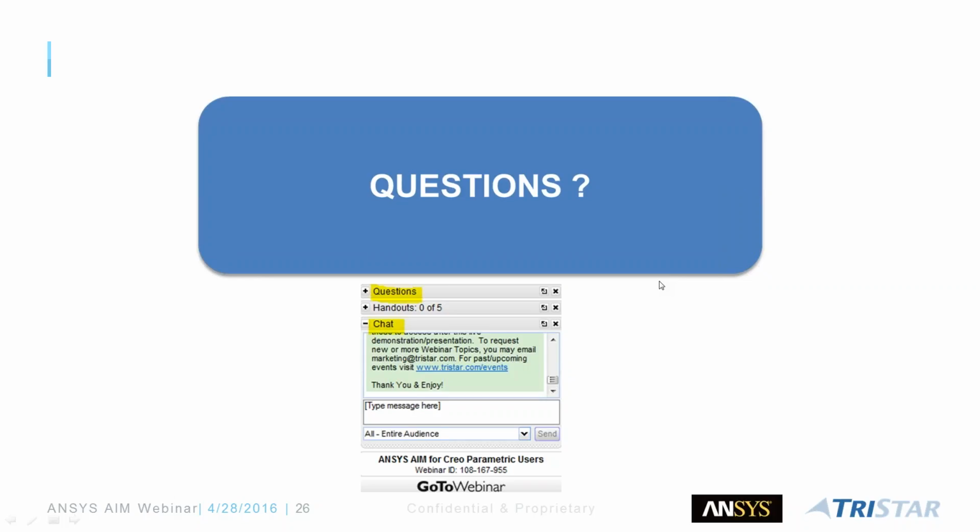Is there a way to create a volume extract in Creo so as to avoid learning SpaceClaim? That's a good question. Yes, you can. However, you have to be good at surface modeling. As you know, within Creo Parametric, we don't have a direct fluid volume extract option. You have to do a copy surface, right? You'll have to do an all solid surface copy, and then using the seed and boundary option, for example, you'll have to get rid of the surfaces that you don't want. So it's not as simple as SpaceClaim.